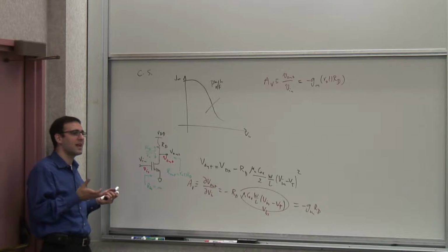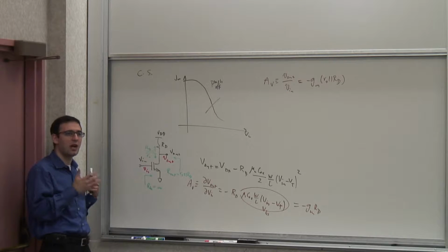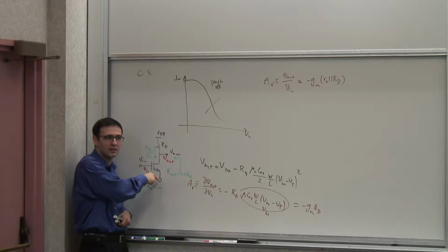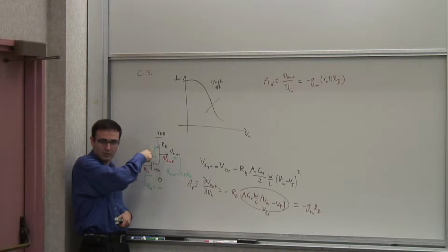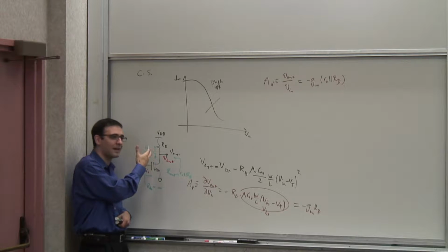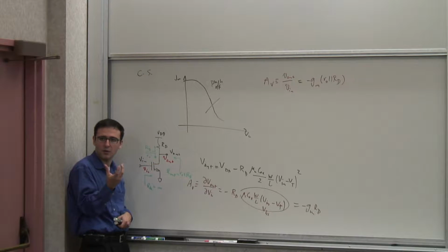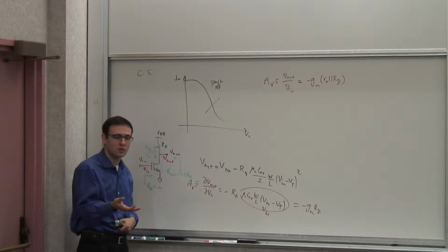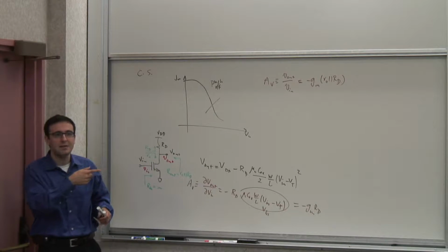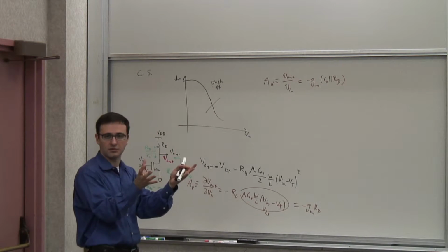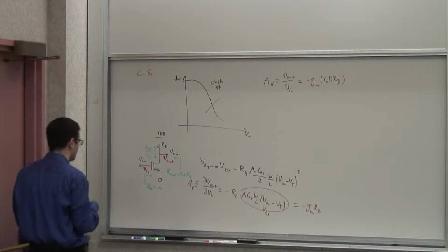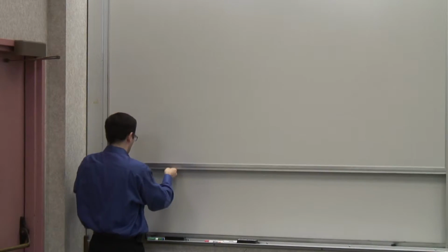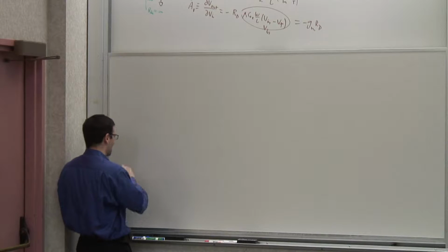So it's good to understand that sometimes we don't have the option of having good resistors, but nonetheless, we look at these stages as basic fundamental building blocks, because even if you have something else here to emulate the resistor, or here, as we'll see today, there is still, from a small signal perspective, some resistance associated with that. And that resistance can be used in this model to predict the behavior, at least from a small signal perspective. So when I show a resistor here or there, it may be the resistance associated with some other circuitry involved in it. And we'll see some examples of that today. But now let's look at the degenerate case, which basically is when you have a source resistor, and we did that too last time.